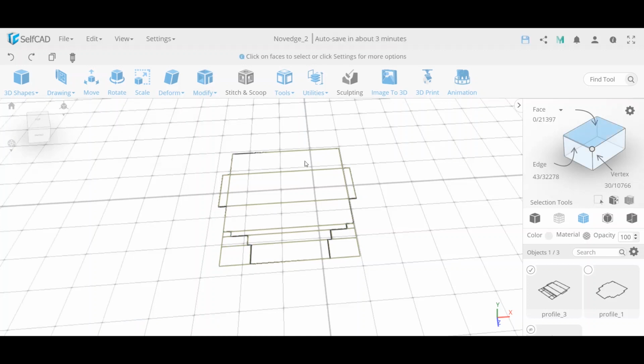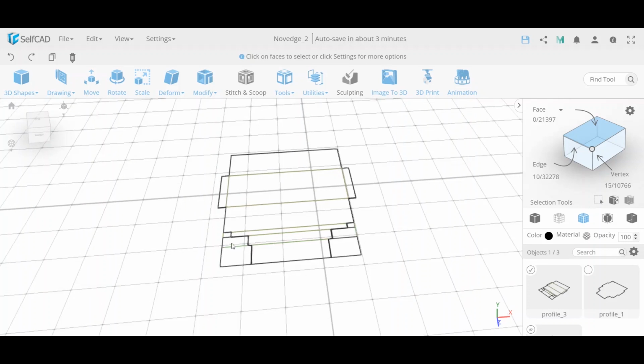Now I can go to select over here these pieces, which basically I'm just going to trim away, all of the extra pieces. You can see this actually makes it quite easy to design something like this. I just need to remember which pieces to cut out. Okay, so this piece, this piece, this. And here I want to show you something. You see this actually selects both of them because it finds the minimum cycle polygons. In this case, if I go to edge mode, it would find just one edge at a time. So I can still select it this way, or I can go to polygon mode and find the minimum polygon cycles.